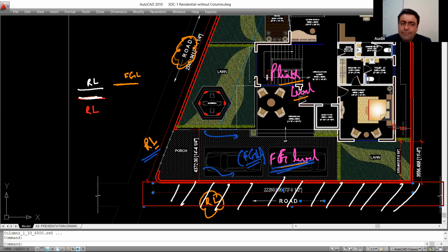Then maybe the next time the road gets repaired, again they will just put a new layer on top of this. So now your road level goes above your FGL. So now every time the rain falls, the storm water very easily enters your porch. This is a very common problem that you see, isn't it? Therefore, what we try to do is take some contingency to begin with.